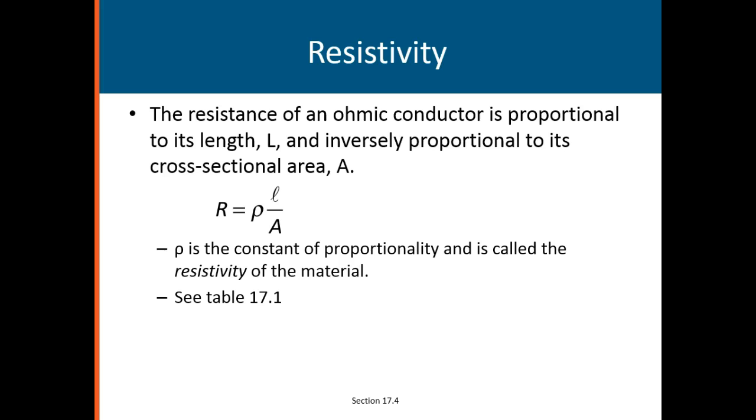Wait a minute. I think they got this wrong. Voltage applied across the ends of a nichrome heater wire having cross-sectional area A and length L. The same voltage applied to the ends of the second nichrome heater wire having cross-sectional area A, length 2L. Which wire gets hotter? They say the shorter wire does. No way. The longer wire does.